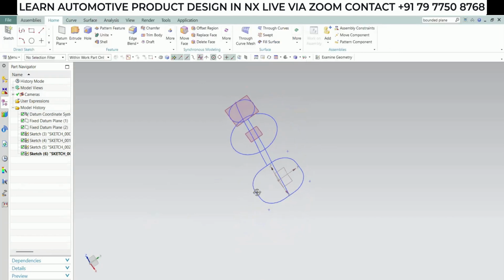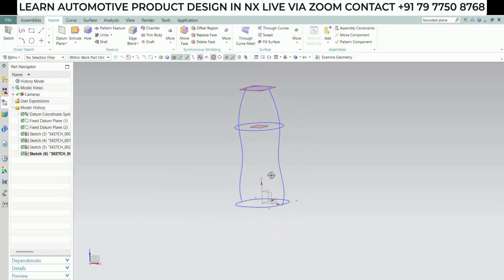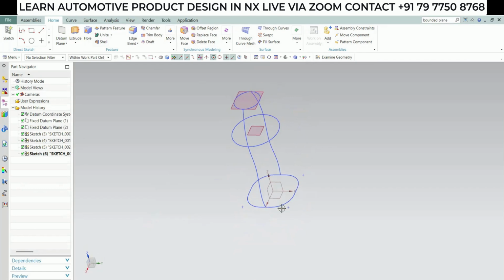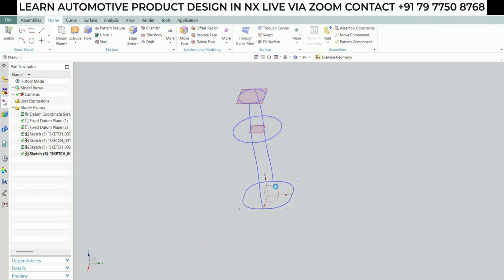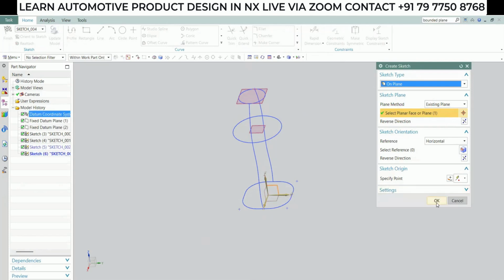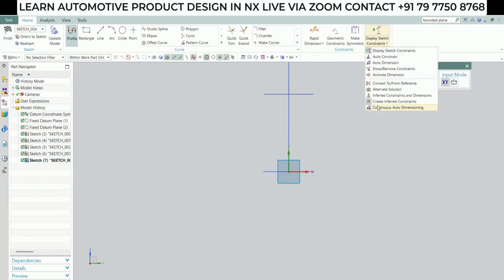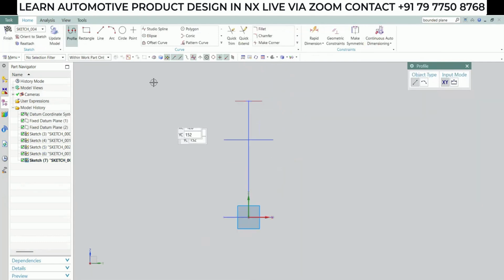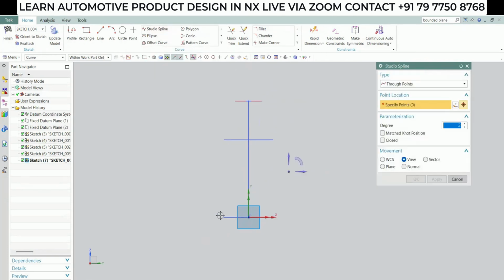And similarly you need to take the other vertical plane. So this side we have done now. So now let's try to do it with YX plane, or sorry, YZ plane. Same curve we need to do. Just say OK, pick the YZ plane and then just say OK. Turn off auto dimension. Same strategy. Pick 5 points. Same thing that we need to do here.